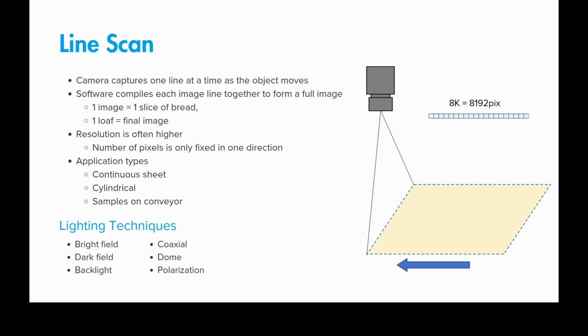If you were going to take that same bottle and look at it with an area scan camera, you would have to have anywhere from 3 to 4 cameras looking all around the bottle, and then the images you're going to get are going to be 4 separate images with a little bit of distortion and curvature around the edges. You might not be able to see the whole label in one. Even with all 4 images, you might miss something.